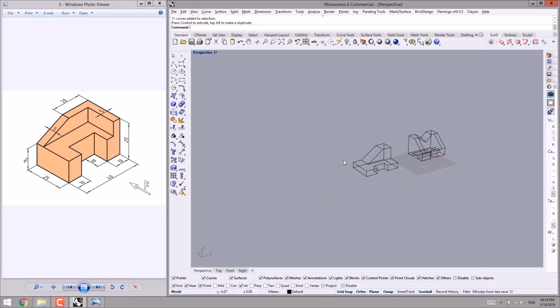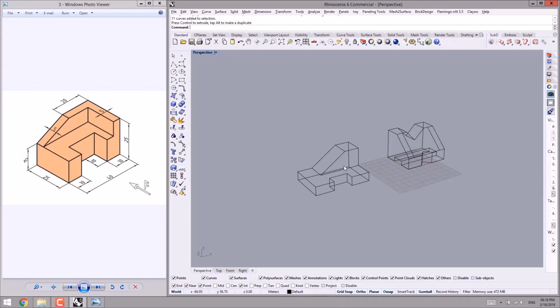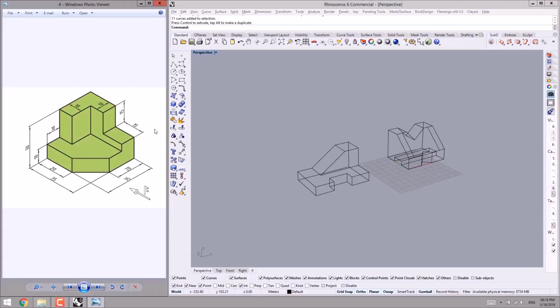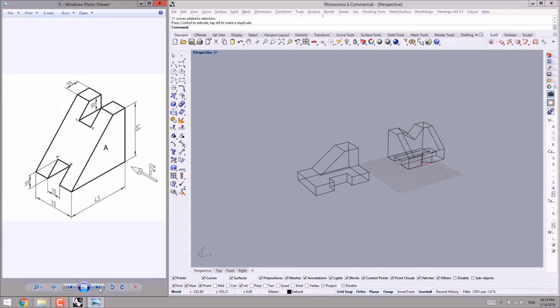But for you, in addition to these two practices or homeworks, for developing your skills in sketching 3D lines and using ortho, that how and when we should use ortho command or options, and how can we sketch vertical lines, specify angles, relative coordinates, and the length and distance.